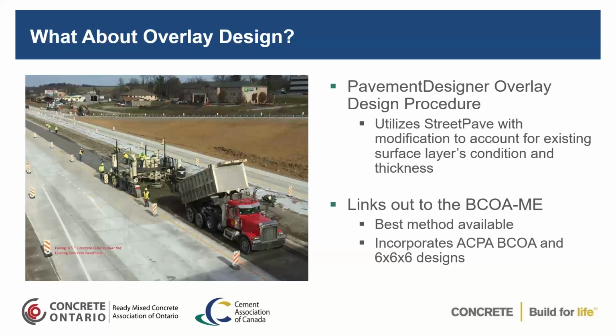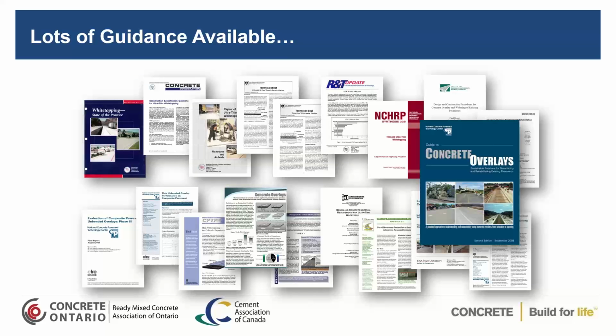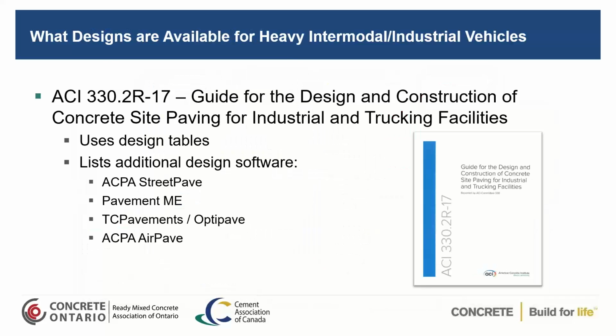I just have a few slides on overlays. The overlay designs are based on utilizing the StreetPave, but it also references the BCOA, that's the bonded concrete overlay of asphalt. A mechanistic approach was developed by the University of Pittsburgh, Julie Vandenbush. It uses that method to do the design for concrete overlays. There's also a lot of documentation out there on concrete overlays that can be looked at.